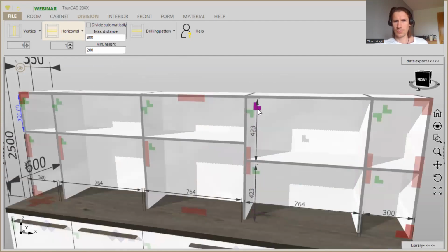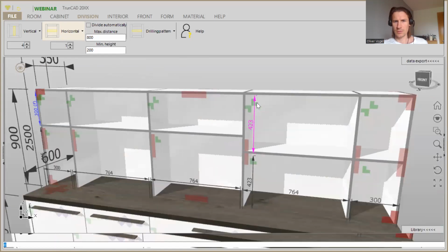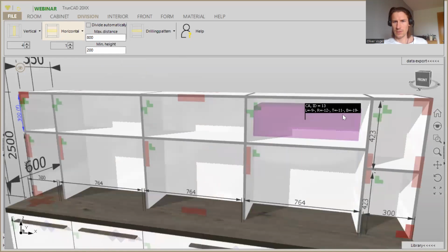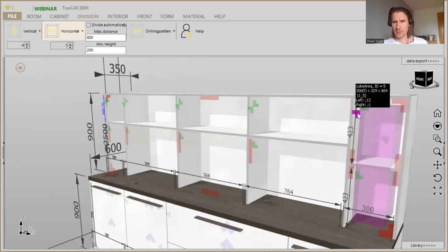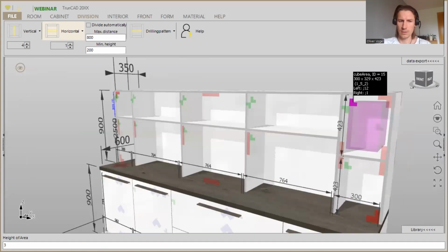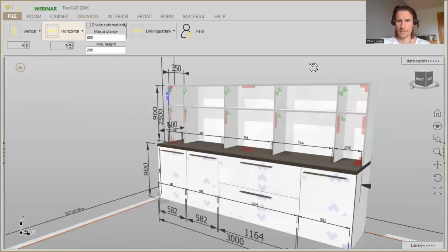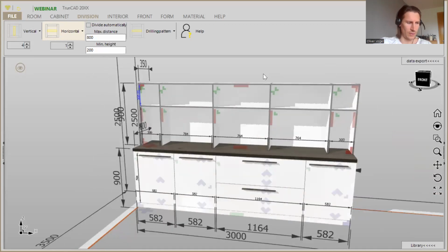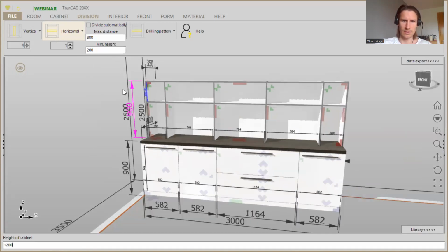Here's also important that you click here on the dimension or on the right smart click. Here you see we have here the area for the whole, smart click for the whole area, and here for the top right area. That is what we need. And click here on height and type in 300, and here we are. So I've just noticed that we have here 1200 height.